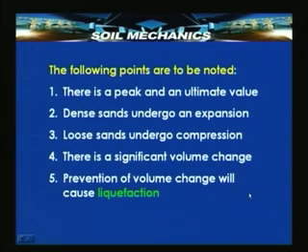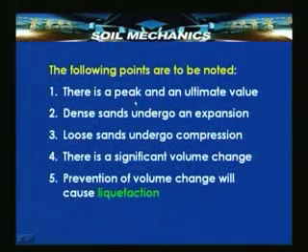So, with respect to the behavior of a soil, whether it is cohesionless or cohesive, under shear we can see a few special points which are summarized here. One, there is a peak and an ultimate, which we saw in the previous diagram. Dense sands undergo expansion mostly, although they undergo a little bit of compression initially. Loose sands undergo compression. There is a significant volume change. The amount of compression or expansion is quite significant under shear.